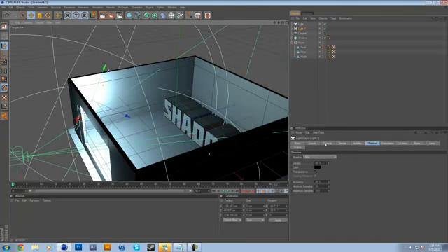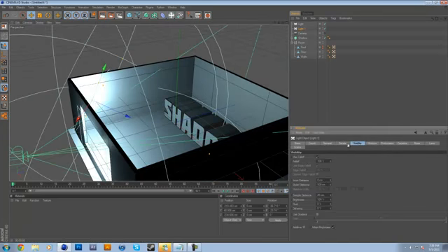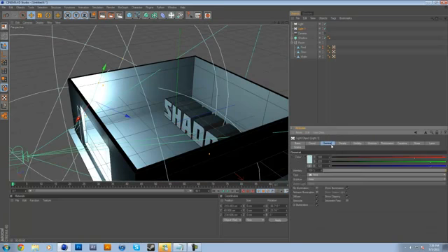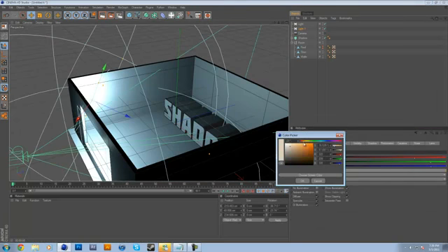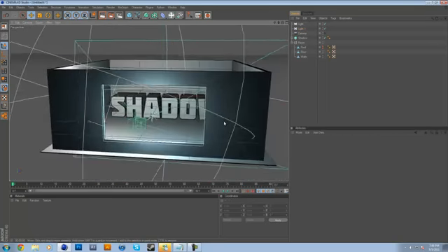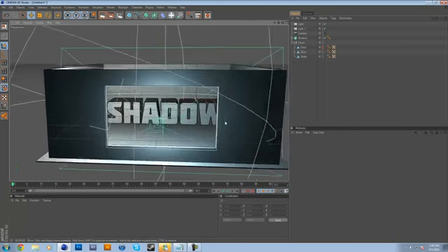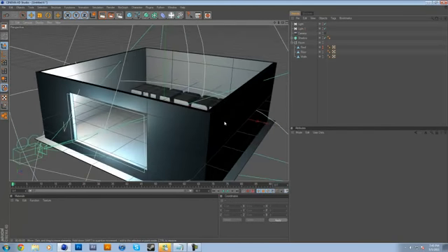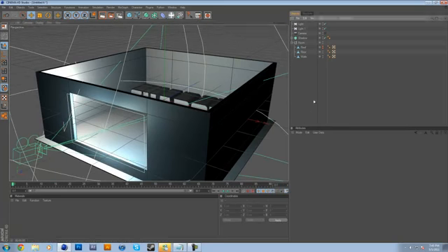So we'll make a second light, it's going to be our fill light. We'll leave all these settings, the details and the shadow tabs the same. Just change the color to maybe a yellowish or an orange, something like that, just to give some variation in the lighting. So that's about it for the lighting. Very simple sort of lighting setup.